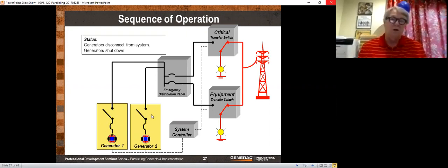But in this case, all of those generators all have the master controller right in the generator controller. Synchronization and paralleling is done very, very quickly. So typically what you will have is you have a power outage. All of a sudden, all the generators start, and then it will be maybe 5 seconds before all those generators are up and stabilized and producing the right voltage and frequency. Then the first one that arrived will go ahead and close. And once the system bus is energized, then all of the others synchronize and parallel independently. So you will hear it stop, and then you hear a click as the first contactor closes, and then all of the rest of them synchronize. It takes a second or two, and then all of the other generators parallel.